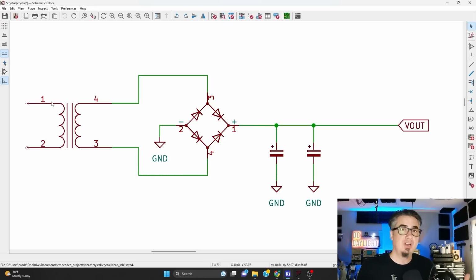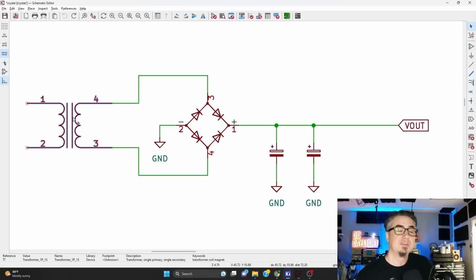So basically you have 120 volts or 220 volts somewhere in between, depending on where you live, and the frequency that is delivered to you could be 50 or 60 hertz. Here in the US, 120 and 60 hertz. So we want to step that down usually to operate our lower voltage DC stuff. So we need a nice, clean, stable DC voltage. So we start off with usually a transformer. Okay, so that provides us isolation from the mains circuit, but also steps down our voltage.